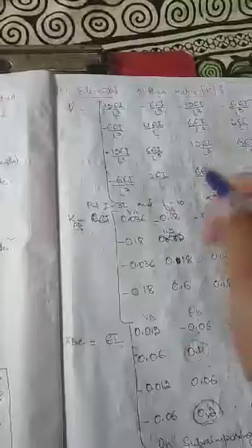So I think you got the direct stiffness method. This is a very simple method. So you have to only concentrate on the steps. How to do the steps? First you have to calculate the degrees of freedom, then assign the element coordinates, then global coordinates. After that, then you have to assign the elemental stiffness matrix K. You have to remember this formula by heart.